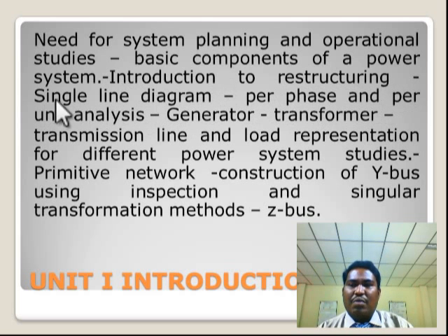And we have to represent our entire power system as a single line diagram. Whatever the quantities are, whether generator, motor, transmission line, or bus bars, we have to express them in the format of a single line diagram, and we have to express the single line diagram in per phase and per unit analysis.